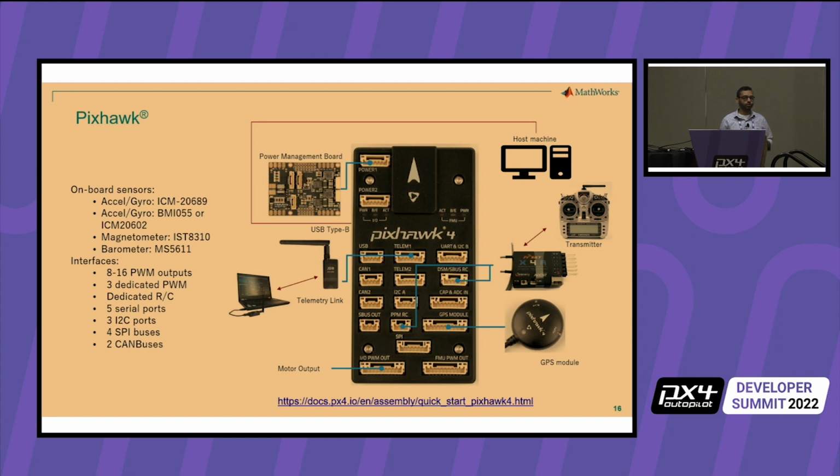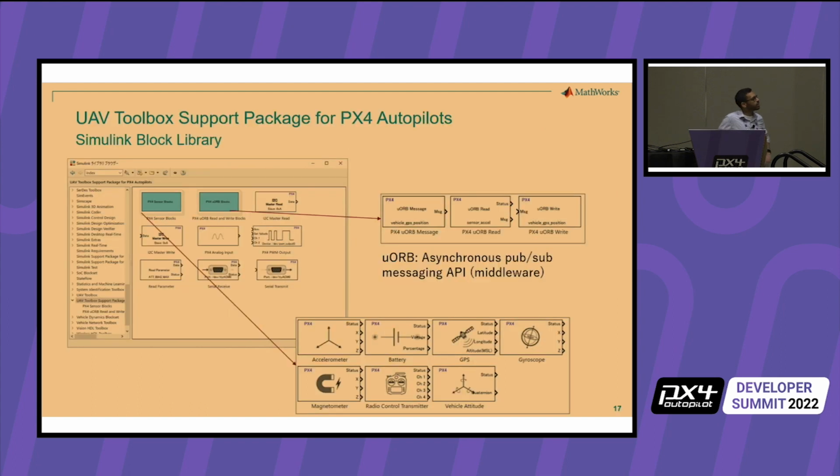Simulink and MATLAB actually don't just work with the Pixhawk. We can work with anything that runs the PX4 firmware. So if you want to just use your own stock and use the FMU that comes from the PX4, you can use those. You don't have to go with the Pixhawk itself. So going further, let's take a look at what we provide out of the box from Simulink. Here you can see that there's a ton of blocks that we provide, both for communication, and ways to read directly from the Pixhawk itself.